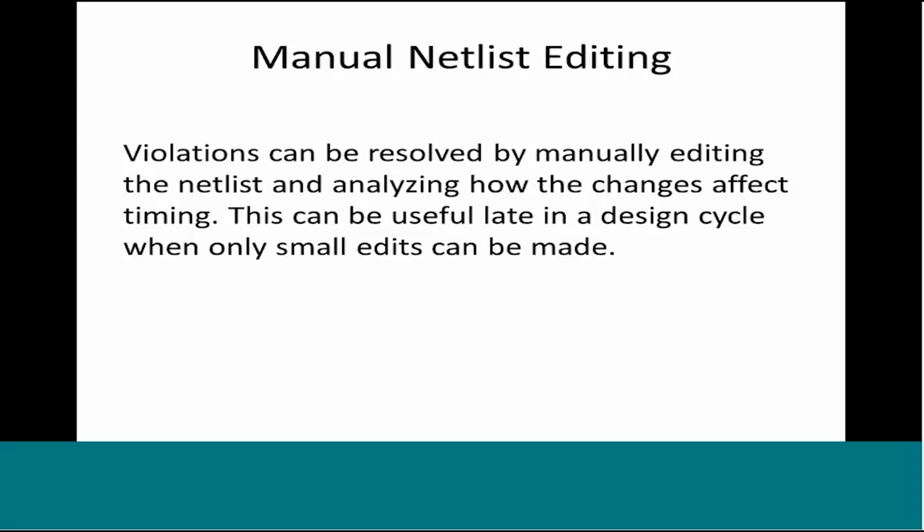We will not go into a lot of operational details because it's an advanced topic. I'm just explaining the concept here. These commands are used to manually edit the netlist only temporarily in the PrimeTime session. You don't write out the netlist, and you can analyze timing within the session itself.